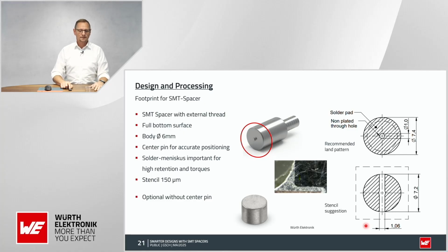Why this? Imagine you have a PCB where you can't use bore holes, like IMS PCB with a metal substrate, which is used commonly for LED boards, for cooling effects. With a solder connection through the borehole, this would lead to a nice shortcut.